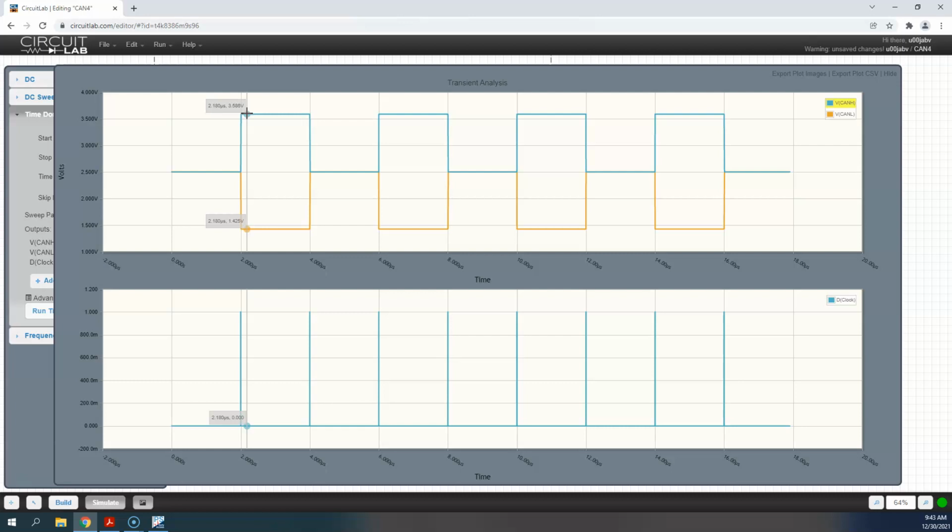And let's say that the engine controller has a crucial message that it needs to get out. Or from the transmission, that a shift is in progress or we're approaching a shift. If we're on-road trucks, something like an ABS event is a very high priority message. For lots of machines, the engine torque speed command, what I want the engine speed and torque to be, is coming from some vehicle controller or transmission controller. Those messages are critical, much more important than this radio message. But the radio is using the bus.